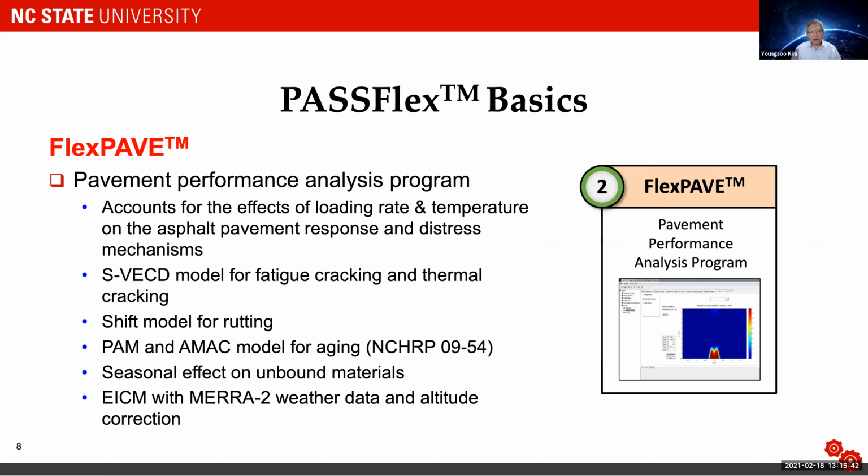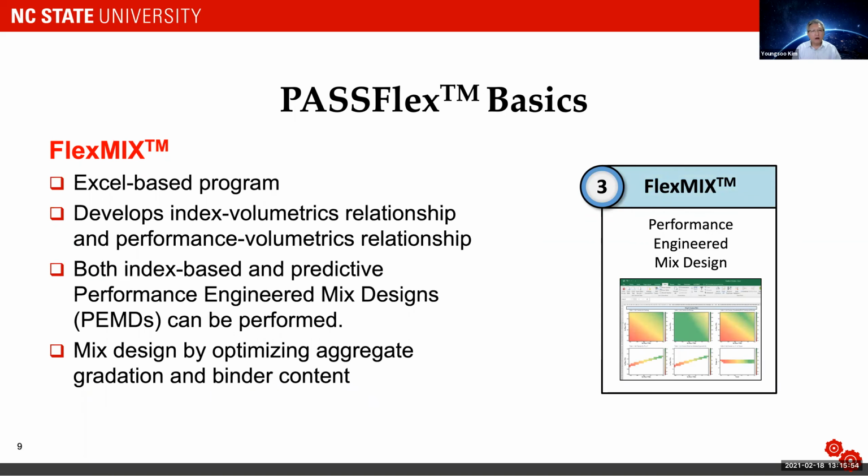Right now, we are doing the reasonableness check of FlexPave version 2.0, and FlexPave version 2.0 will be an Excel-based program. FlexMix is also Excel-based. So as you can see, FlexMat to FlexPave to FlexMix, they are all Excel-based programs, and it develops IVR and PBR that I'm going to talk about today. And you can do index-based PEMD or predictive PEMD using PBR. And here we use the Bailey method, and by using these relationships, we can optimize aggregate gradation and binder content.